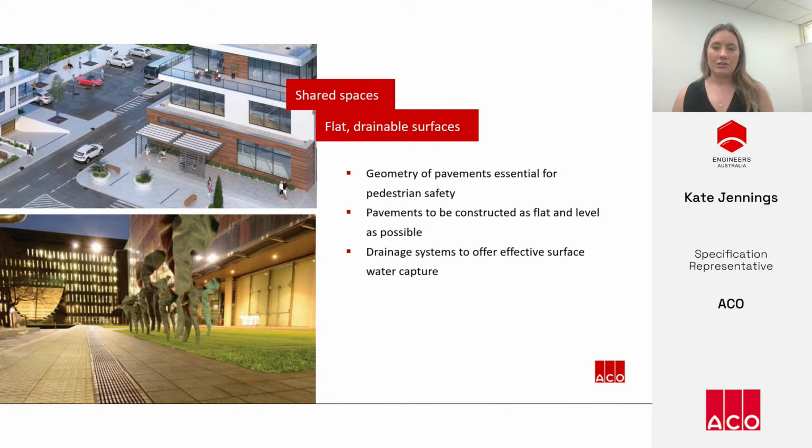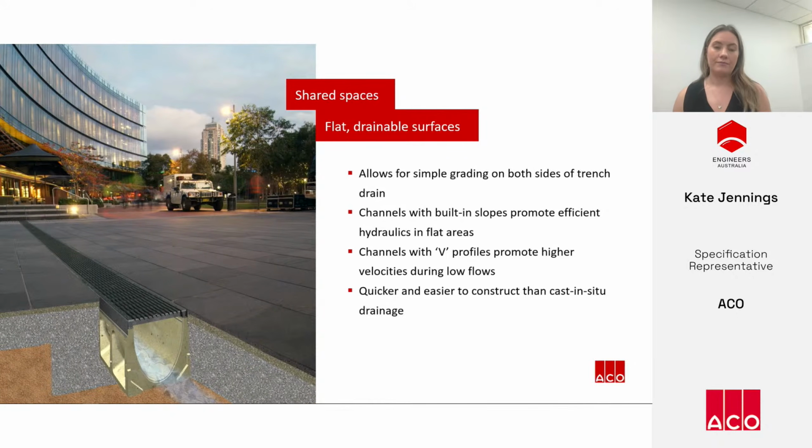Uneven or steep pedestrian spaces will create trip hazards, particularly for the elderly, children, or those with a disability. Surface water management often leads designers to create steep pavements, but they can be designed flat if drainage is properly considered and incorporated during the design phase. A way to achieve a flat pavement is to use a graded trench drain with built-in slopes. This promotes efficient drainage of the surface.